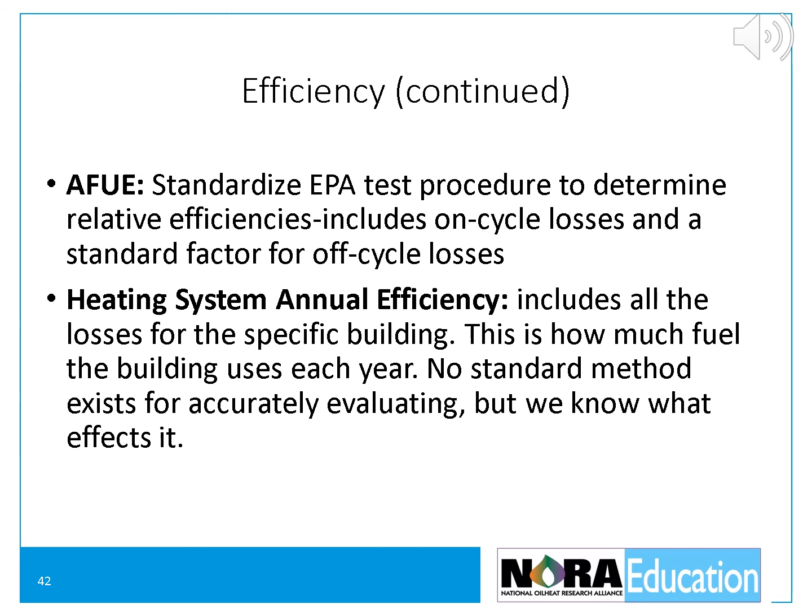Unfortunately, equipment manufactured before 1985 does not have an AFUE rating and cannot be compared to today's equipment without further analysis. The objective of the AFUE labeling program is to supply consistent efficiency information to help consumers select and install high efficiency equipment. While there are some serious flaws in this procedure, it is the only consistent information available for comparing units. AFUE indicates the efficiency of the burner-boiler or burner-furnace combination for a set of operating conditions.